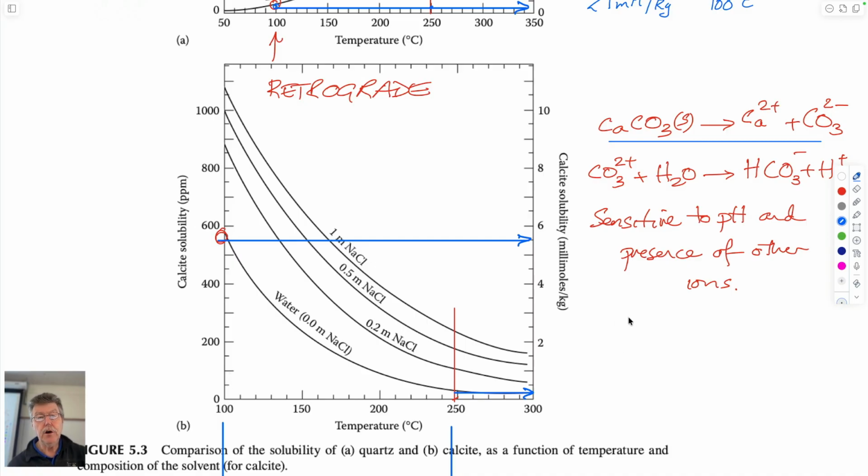If you go at 250 degrees C, we have something in four millimoles in water. So this is brine. These are all brines. This is pure water. So if you flash it to steam and re-inject it after condensing it, you might expect that it didn't have very much dissolved material in it, and so it would go back in as basically just distilled water.